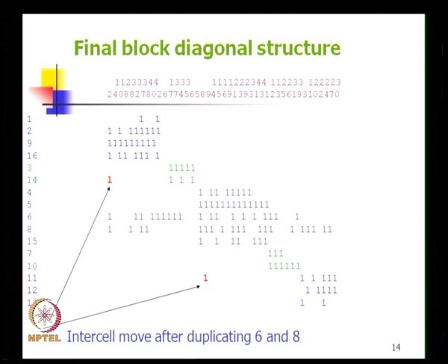Secondly, the sequence of visits is also not known, and the cell invariably has products moving in a unidirectional flow. So either if there are reentrant flows, or if we have a situation where the route or the order of visiting the machine changes the requirement, we may have to add machines into this cell. So line layout addresses all these issues, and we will now see how we address some of these issues through some examples.